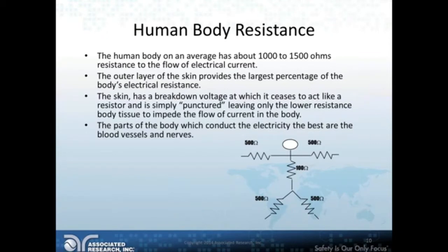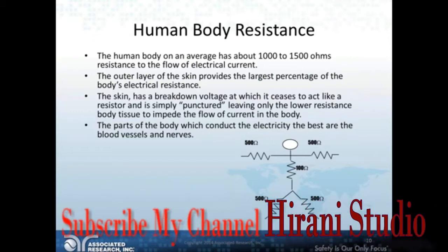Fingertip to fingertip contact, I just did this the other day, and I got about 500,000 ohms. But if I lick my fingers or lick my hands and put it on there, it goes down to 100,000, maybe 50,000. So you can see just that wet surface will provide a much lower body resistance. And that's why I say to keep in mind that different conditions are going to have a great effect on how much current you're actually exposed to.